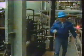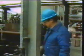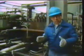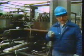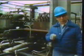Commonly, you'll find two main types of compressors in use today, the dynamic and positive displacement. Now, the most common positive displacement compressor is a reciprocating compressor, and the most common dynamic compressor is a centrifugal compressor. Every day, someone around us uses some kind of centrifugal compressor right in their own home. This hairdryer, for instance, is a type of centrifugal compressor with a heater. Even this vacuum cleaner is a type of centrifugal compressor.